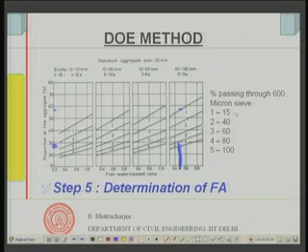That means this one is a better graded sand rather than this, because in this case everything is fine size. In this case there is a mixture of everything, there is 15% above 600 micron. Somewhere here would be a better situation, 15-60% possibly above 600 micron, but this is a coarser side. So, you have got larger size also there in this particular one.